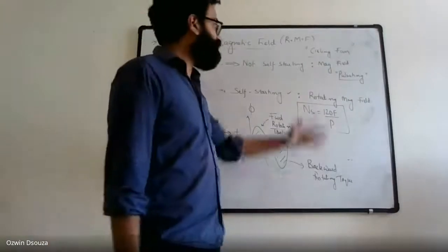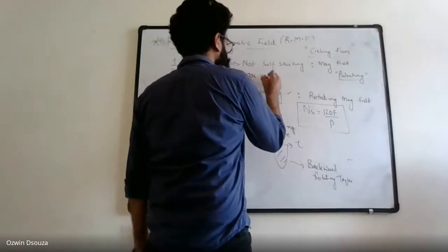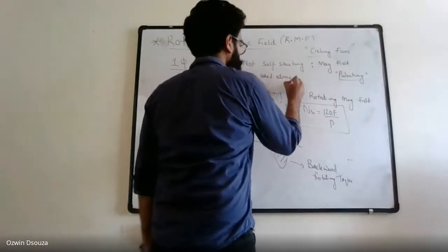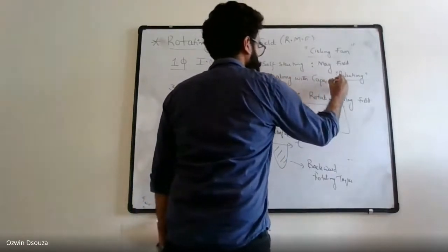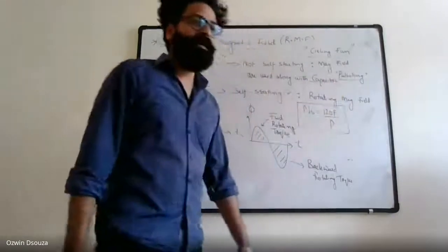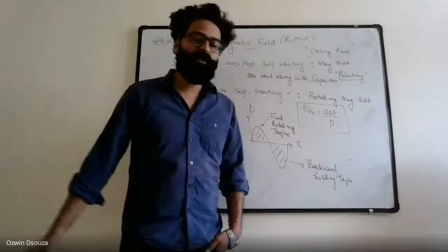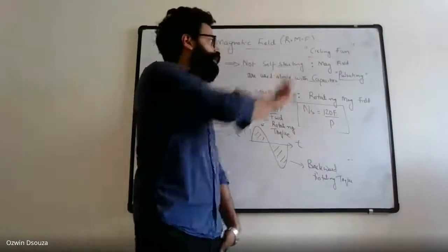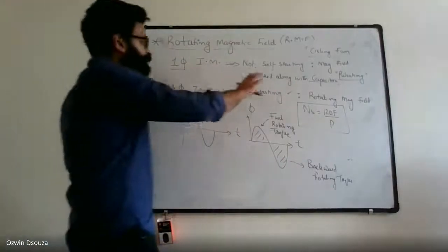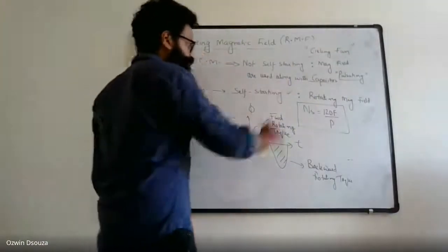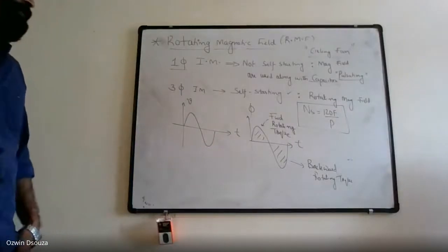So that's the reason all single phase motors are used along with capacitors. These capacitors basically serve as the starting mechanism for the induction motors, and they are widely used in ceiling fans as well. All right. So that is about the pulsating torque and the non-self-starting capability of single-phase induction motor.